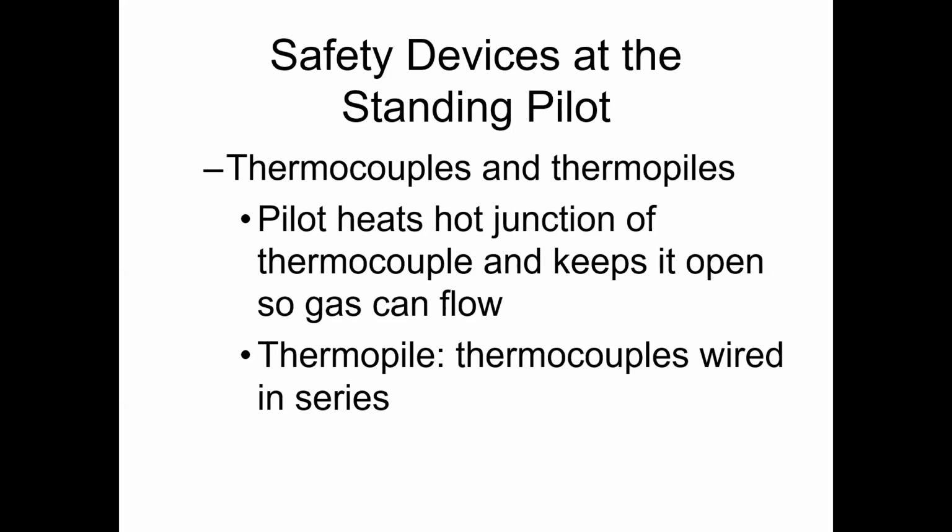The thermocouple is going to take that heat energy, that flame, and convert it to an electric energy, and then it's going to send that signal to your gas valve to make sure that that gas keeps flowing until it stops sensing it. And when will it stop sensing it? When the flame either goes out, or when the thermocouple starts to malfunction. And the most common way that a thermocouple malfunctions is with soot buildup over the thermocouple.